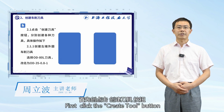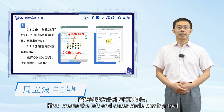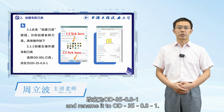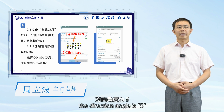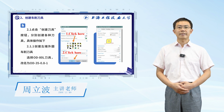First, click the Create Tool button to create various tools respectively. First, create the left-hand outer circle turning tool. Select the OD80L tool and rename it to OD35 0.81. Change the ISO blade shape to rhombus 35. The tip radius is 0.8. The direction angle is 5, and the blade length is 15.